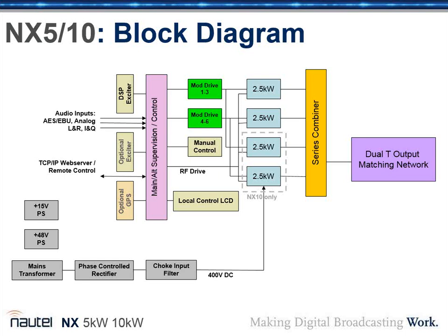There are 2 of the modules in a 5 kilowatt and 10 in a 10 kilowatt, or rather 4 in a 10 kilowatt. Yeah. They use exactly the same kind of driving and the same kind of combiner. It's using 6-phase multi-phase PDM, and we use the same exciter. We have an optional exciter in these units. There's one provided with the transmitter and a second one is optional.